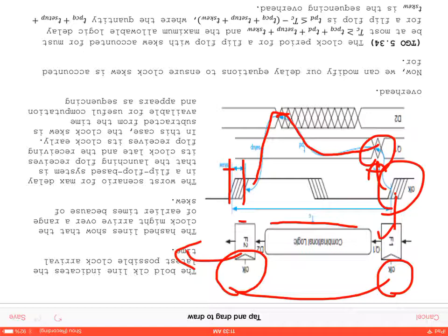clock skew. And the reason why this is clock skew is because that's the amount of time that's required before there's going to be some sort of change in value here that we're not certain is the correct time. This moment here, once T clock skew ends, is the moment we can guarantee the correct value will be on the output. So that's going to be the value that we add to our cycle time in order to ensure that we have properly designed the circuit.